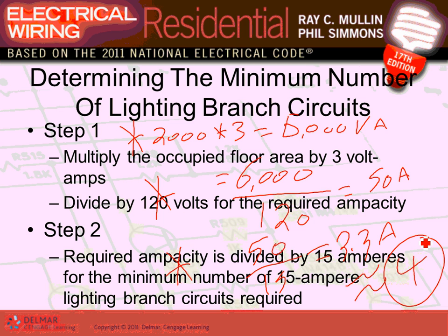That's minimum. Now, what we do, we go a little bit higher than the minimum, guys, and we'll circuit them slightly more. On a 15 amp circuit, it's not a good idea to put more than 9 to 10 receptacles or lights. You know why? Because if one of them trips, you end up with the whole house down, by the way, if you put it on 4 circuits. Lights and small receptacles. There are other dedicated circuits. So, any comments, guys, about the minimum? I can't emphasize the word minimum enough. I can't emphasize the words lighting and small general purpose receptacles enough.